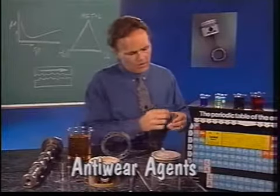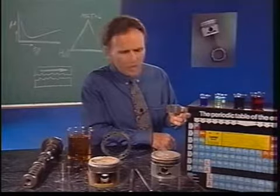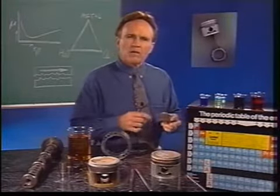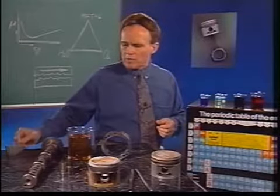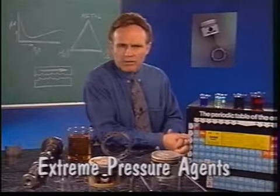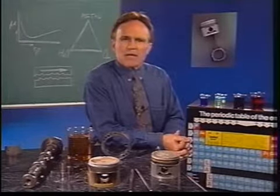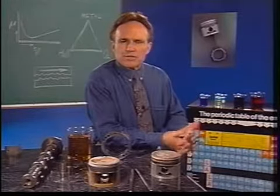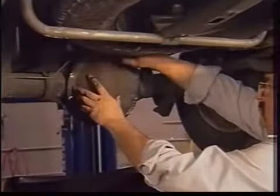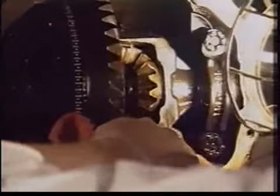Anti-wear agents reduce the loss of metal from component surfaces by preventing metal-to-metal contact under high loads. They include film-forming compounds like zinc dithiophosphates, which protect by reacting with or adsorbing onto metal surfaces. Extreme pressure agents are a special type of anti-wear component for use under extreme loads, low speed and high temperature. They react with asperities on surfaces to reduce friction and wear. These chemicals are especially useful in gear lubricants, greases, metalworking fluids, and other applications where high loads are common.